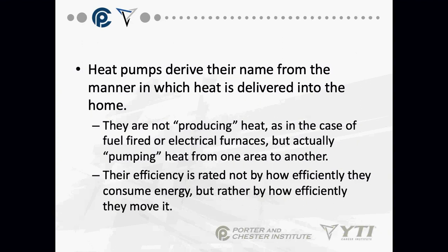Now, why is 32 degrees a magical number if I switch the indoor and the outdoor coil? If all of a sudden my evaporator is outside absorbing heat, why do I care about that 32 degree mark? In winter. Yeah, but why do I care? Yeah, it would be winter. But if my evaporator goes under 32 degrees, what happens? Starts to freeze it. Starts to freeze up. Okay, starts to freeze up.